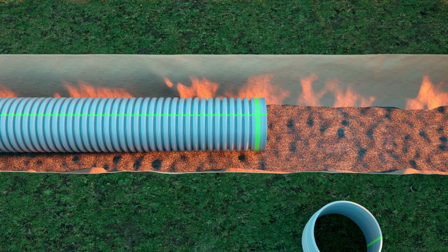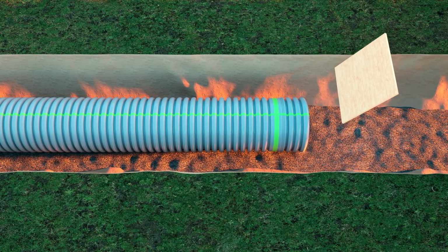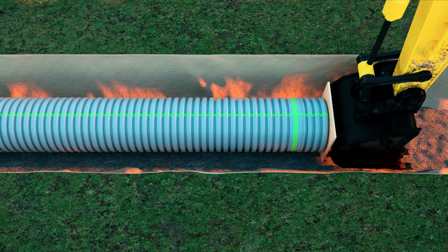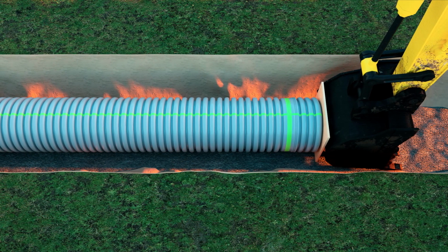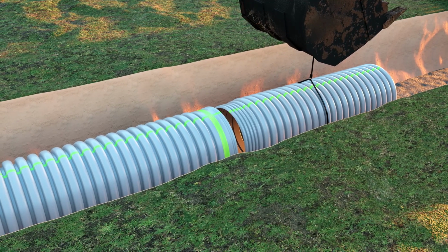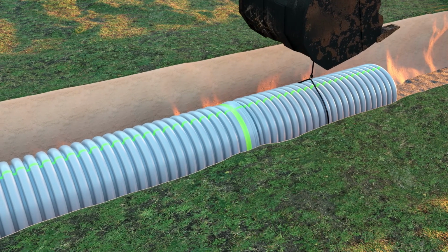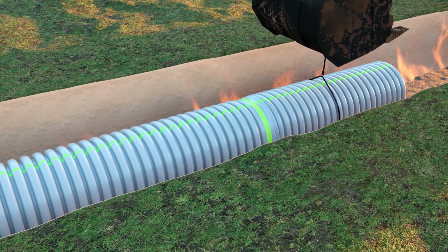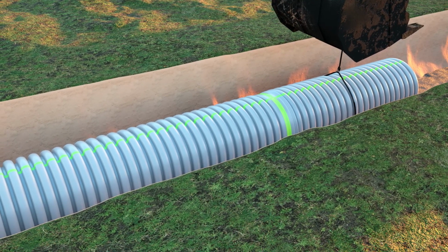For the backhoe method, place the installation stub into the bell end of the pipe and the wood block horizontally across the installation stub. Carefully push the back of the backhoe bucket against the block until the pipe is fully inserted into the bell. The backhoe and sling method requires wrapping a nylon sling around the pipe. Hook the other end of the nylon sling to the backhoe bucket. The operator should carefully push the strap tight toward the bell of the downstream pipe until the spigot is fully inserted into the bell and the home marker on the pipe is not visible. Ensure the pipe is pushed on line and grade to avoid misalignment.